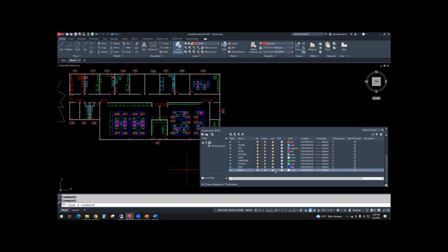So if I was designing the building and then I was handing this over to the interior designer to work on the inside, and I don't want them to mess up my walls, I might lock the wall layer. So if you look at the building here, as I unlock and lock, locking it fades the color of that layer. So it's more of a grayish color. If I hover my cursor over that object, my cursor gets a little lock symbol. So it tells me that it's locked.